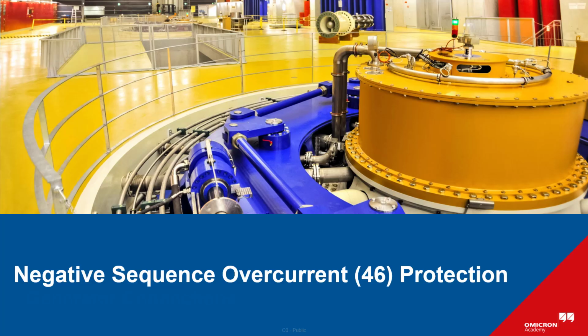In this video we will be focusing on the unbalanced load protection, also known as the negative sequence protection, function 46 in the ANSI code. This protection is essential for detecting and limiting the unbalanced operating conditions that can cause overheating in the rotor.